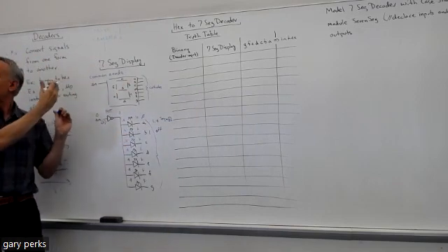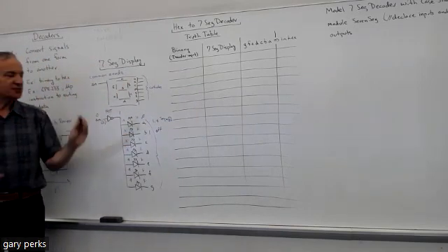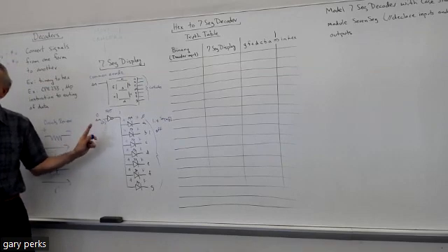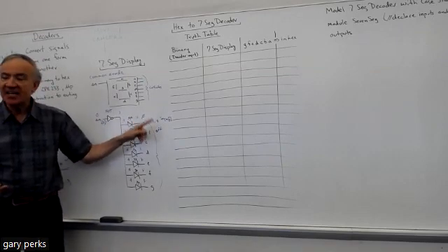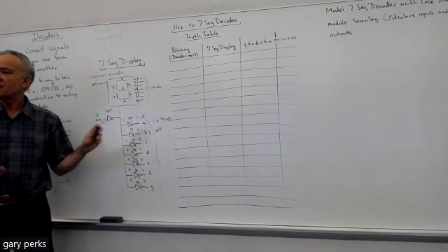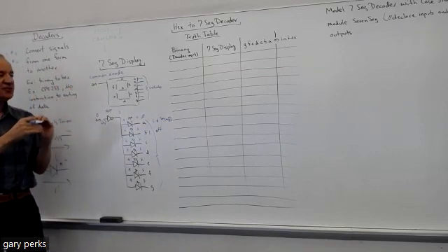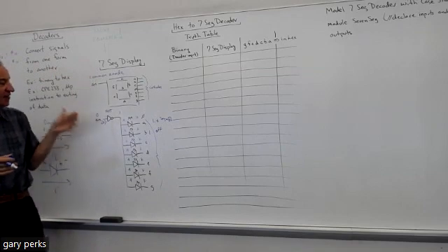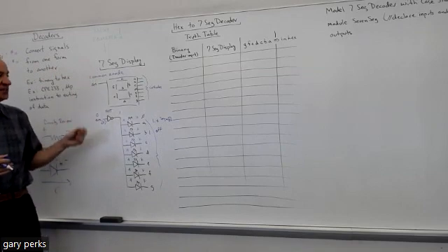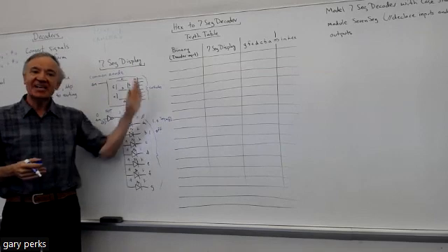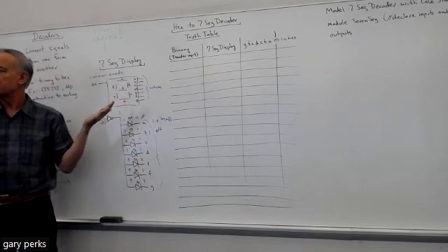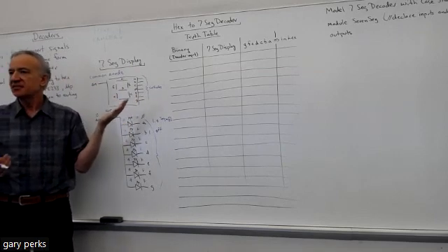To the left of that is the first display, so you'd have AN1, and these would all be seg A1, seg B1, and so on. Then you've got display 2 and display 3. Because there are 4 displays, you have 4 anode inputs and also 4 sets of cathode inputs. Does that make sense?